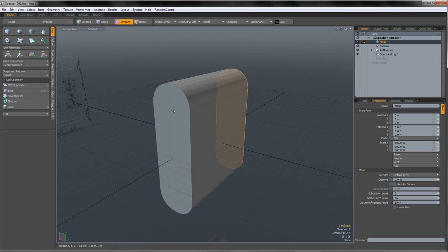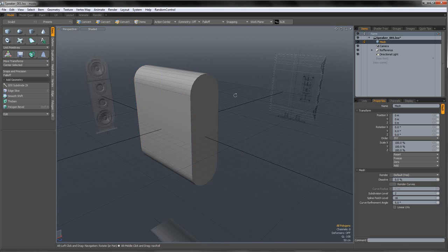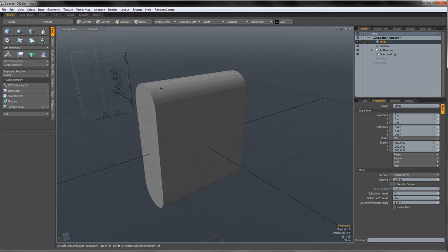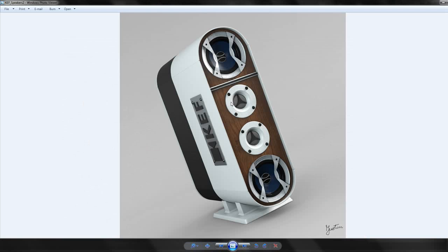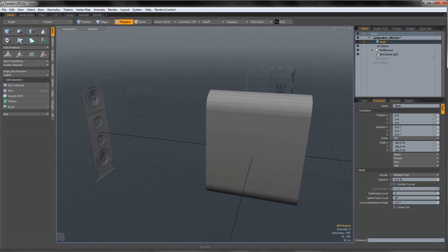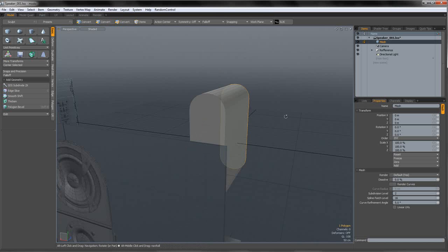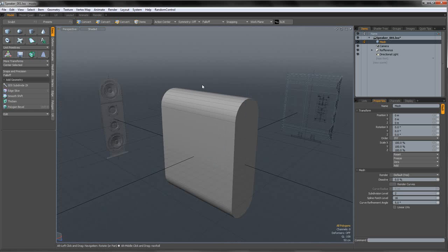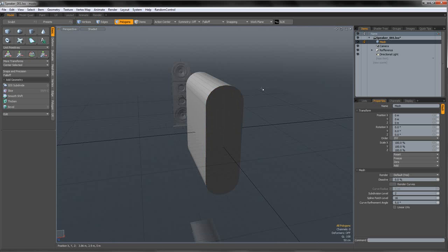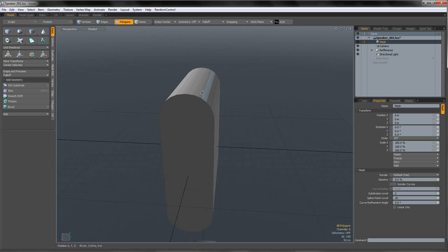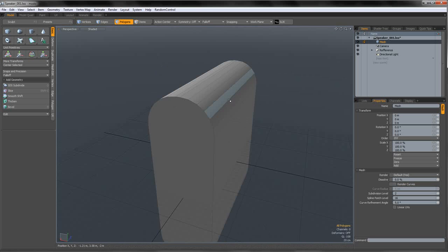Now, the front and the back are separate pieces, so we can either detach them right now, or we can detach them later. But we can probably go ahead and detach them right now using Control X and Control V. That detaches them. Okay. But if you detach them right now, say you wanna hide this one using H on my keyboard.